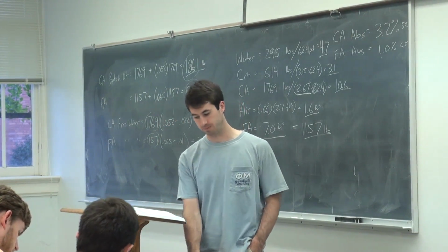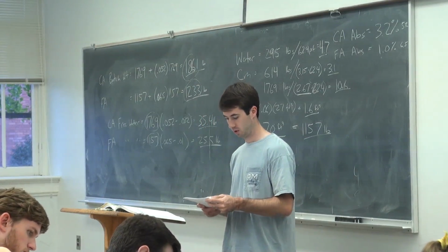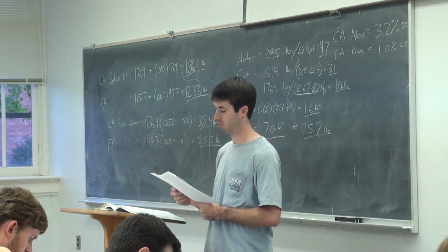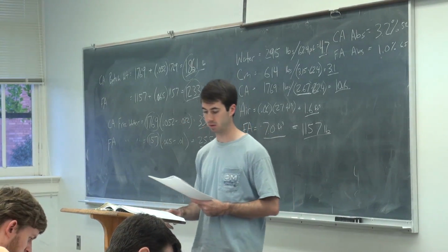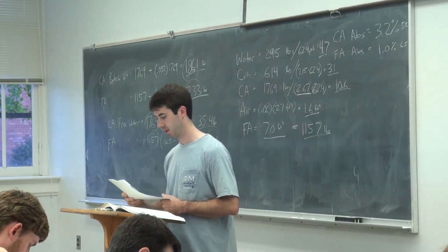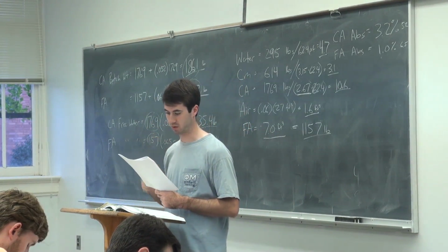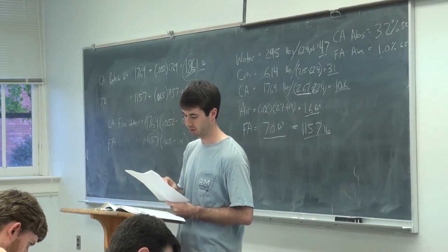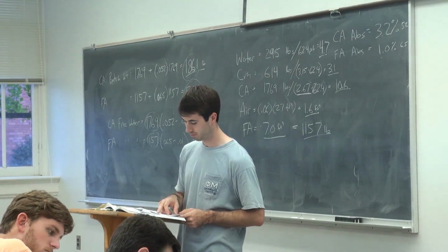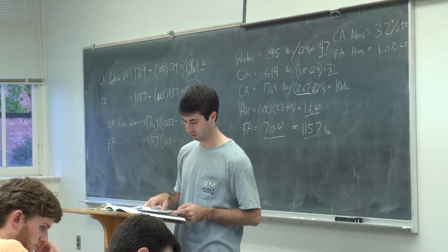So what we're given here, we're asked to calculate the ESALs for basically the following pavement. It had an AADT, average annual daily traffic, during its first year of 12,000 vehicles in both directions, with 50% passenger vehicles, 33% two-axle trucks, 17% three-axle trucks, and their pounds per axle is right over there.